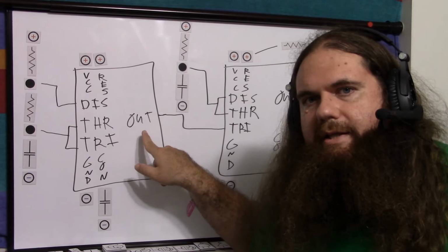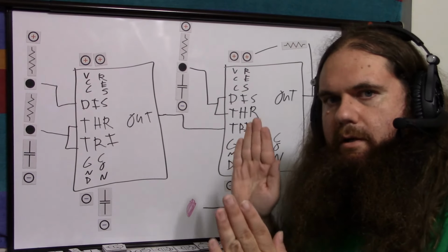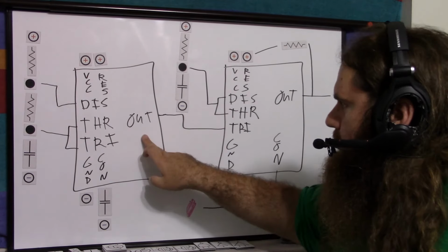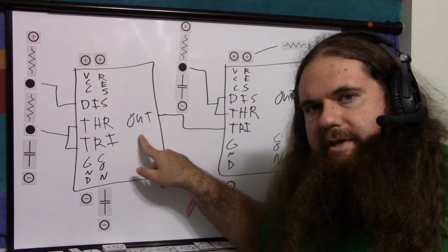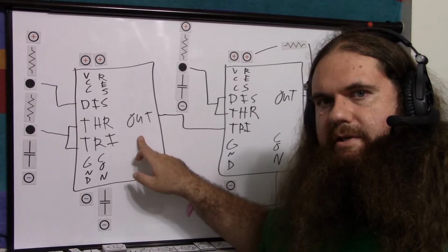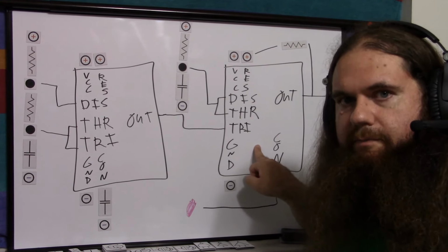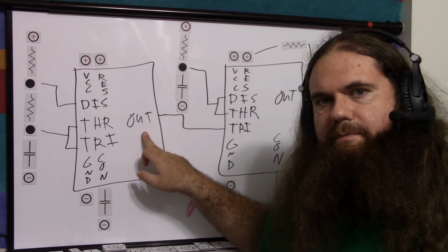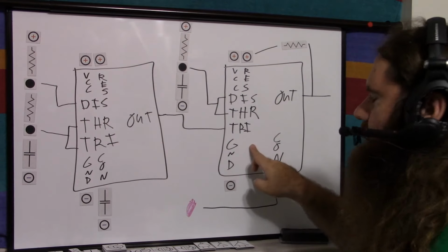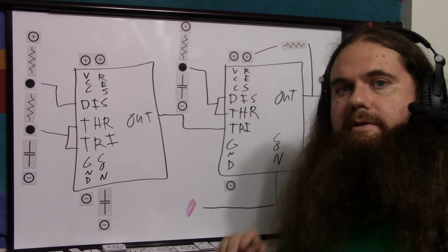So you end up with a limit here. The size of the low pulse is the lowest duty cycle you can have, because the low pulse here becomes a high pulse here. If this is a 75% duty cycle, that means it's low 25% of the time, which means the lowest duty cycle you can have here is 25%, because a 25% duration low signal becomes a 25% duration high signal. You can have longer, but you can't have shorter.